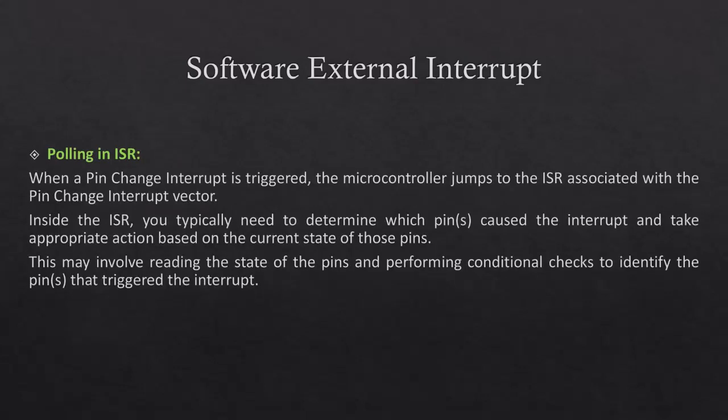Polling in ISR. When a pin change interrupt is triggered, the microcontroller jumps to the ISR associated with the pin change interrupt vector. Inside the ISR, you typically need to determine which pins caused the interrupt and take appropriate action based on the current state of those pins. This may involve reading the state of the pins and performing conditional checks to identify the pins that triggered the interrupt.